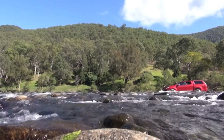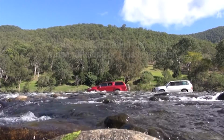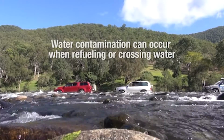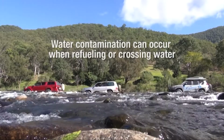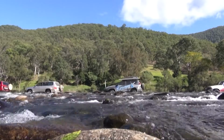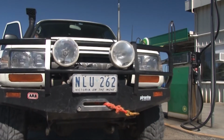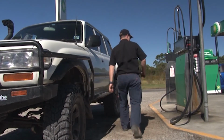Water is the most common contaminant in common rail systems. And how do we get this water in the fuel system? It can come in through a fill and come in through river crossings via the tank breathers, which we'll speak about later. Water coming in through a fuel fill can be caused by water in the bottom of our Bowser storage tanks. This is quite common in the city, is that these Bowser tanks are filled up almost daily now.